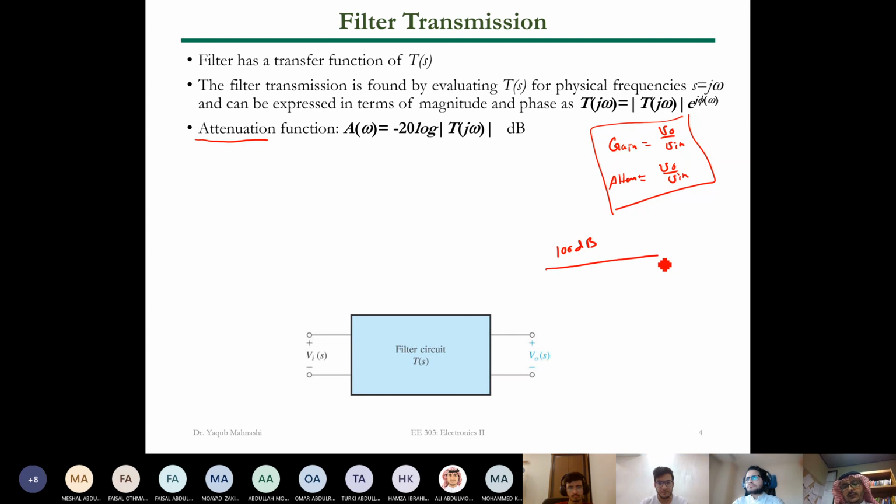If this is the gain of 100 dB, then you have some roll off here, right? So at this point you are getting around 80 dB of gain. So that's the same thing. The signal is attenuated. Instead of having 100 dB gain, now it has 80 dB gain. Right? But at the end of the day, you are measuring V output over V input.